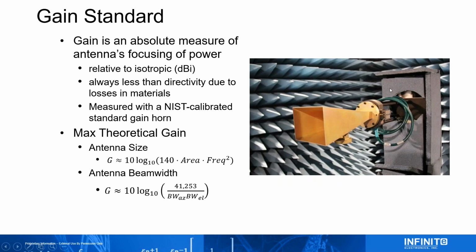So this is how you truly measure the gain of an antenna. Use a NIST calibrated standard gain horn. We know the gain of the horn, and we can determine from that the gain of an antenna.